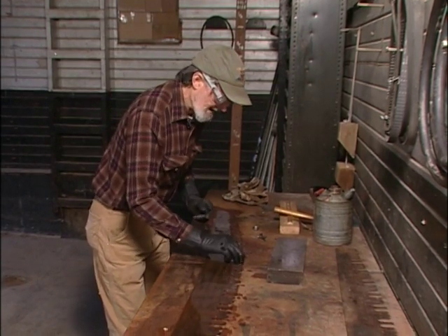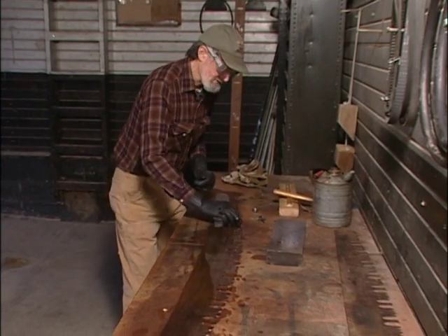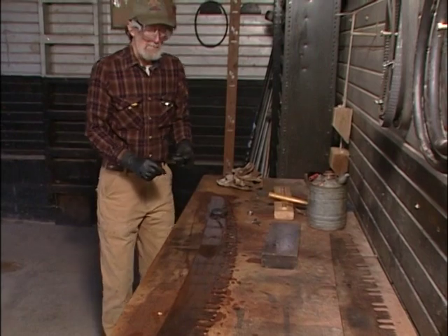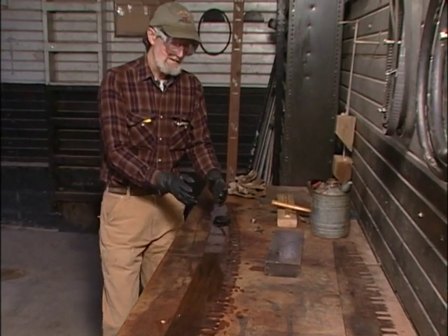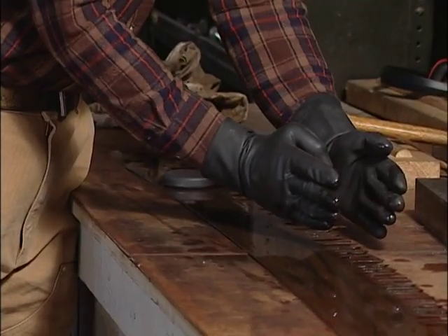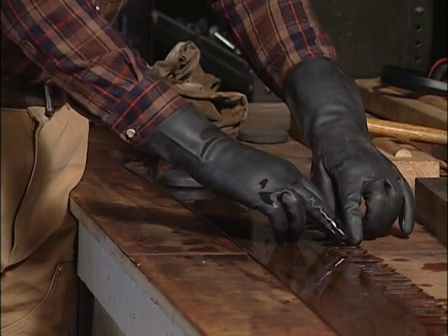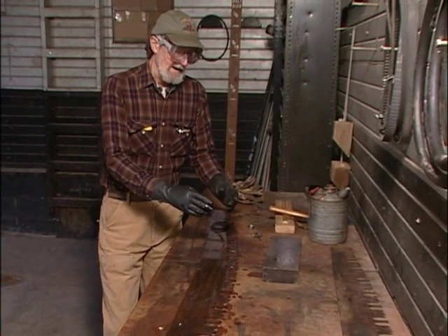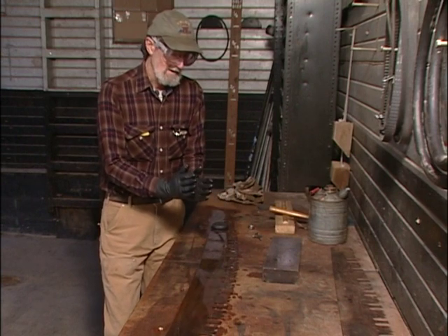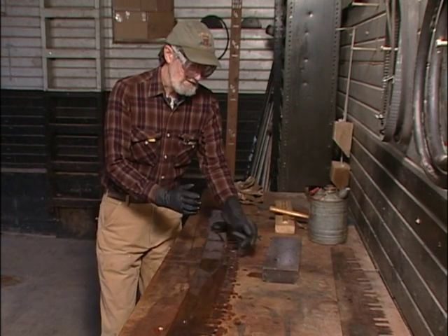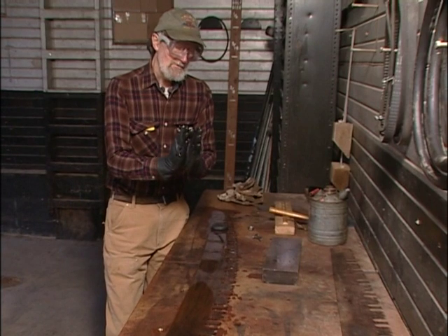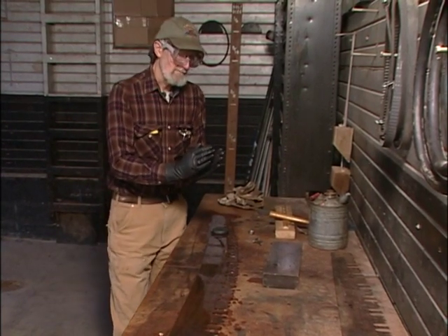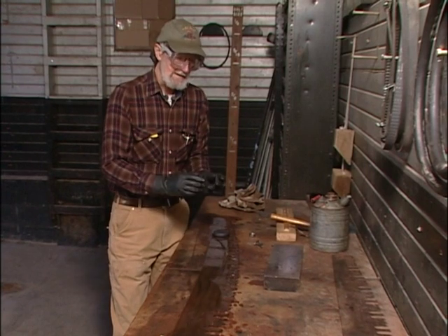And I generally discourage people from using a tool like that because it's very easy, especially with a belt sander, to get it up over the tips of the teeth and really remove material from the tips of the teeth. And that can not only shorten the teeth, but essentially put a reverse set in the tooth, which is very, very difficult to take out.